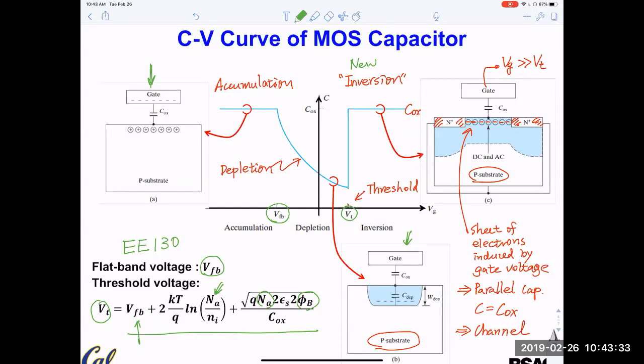So it's a voltage that we can design, and in a transistor, they are also very carefully controlled. Later on, we will see all your transistor characteristics depend on this threshold voltage. In order to have uniform circuits, if you have an IC with 10 billion transistors, and each one of them has a fluctuation of this threshold voltage, well, it's impossible to have an integrated circuit work. So just the fact we can integrate that many transistors suggests we have very precise control of this threshold voltage. It is an engineering feat, the result of decades of engineering effort.